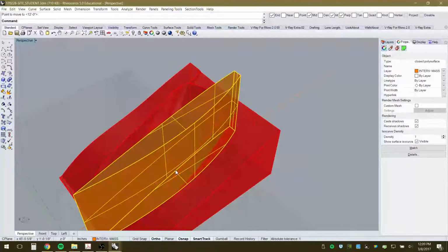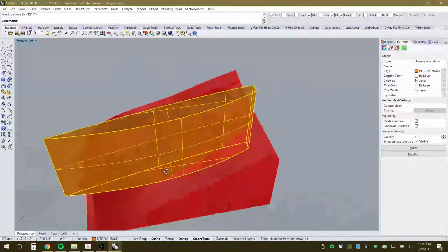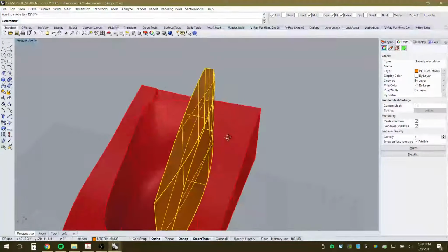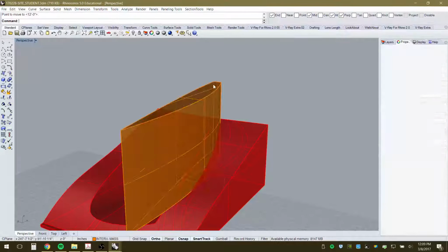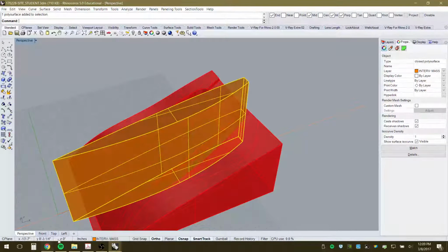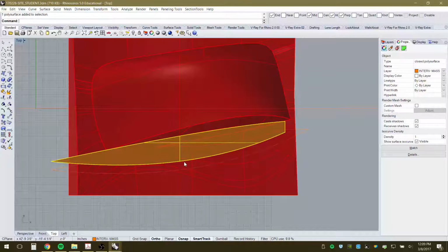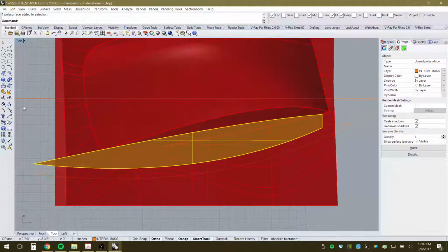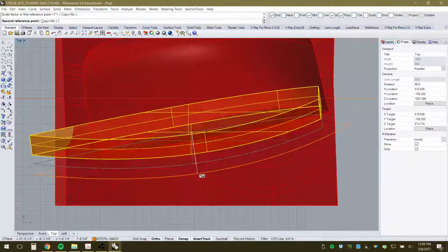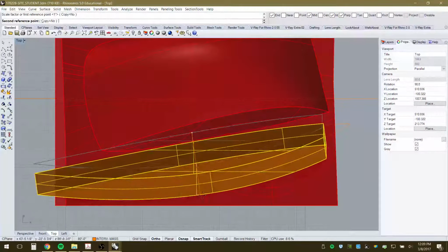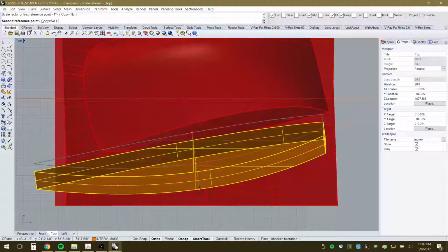It's a little bit of a sliver of an area here, but again, it's a sculpture concept model, so I'm really just sculpting. If I wanted to, I could change the scale of this. Go to the top view. If I wanted this to be more broad, I can go into scale, one dimension, and I can just use this reference point and make it bigger.